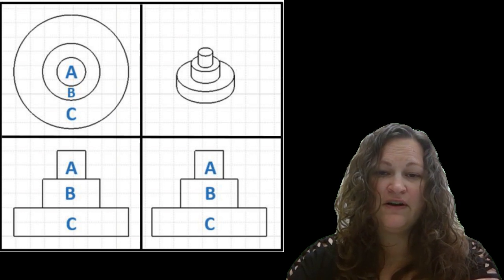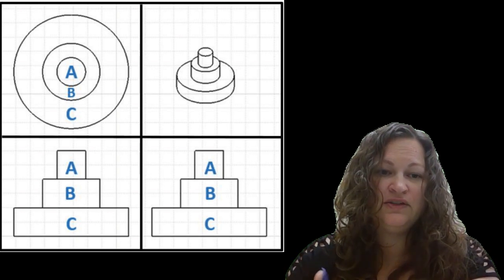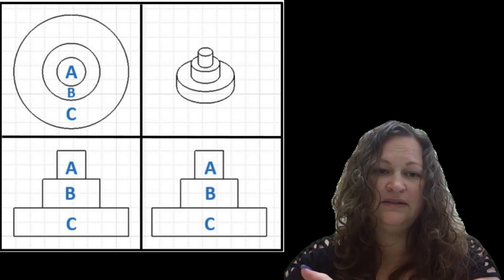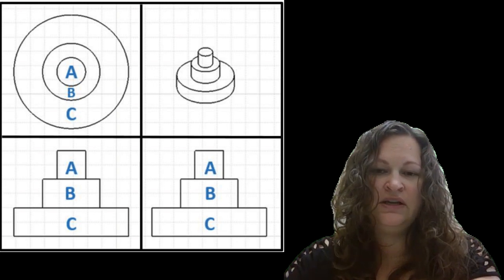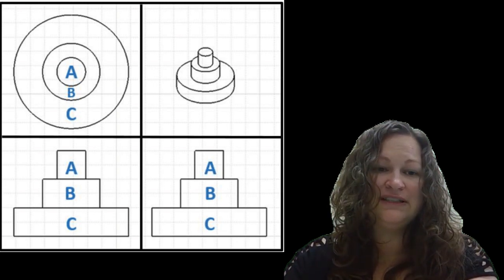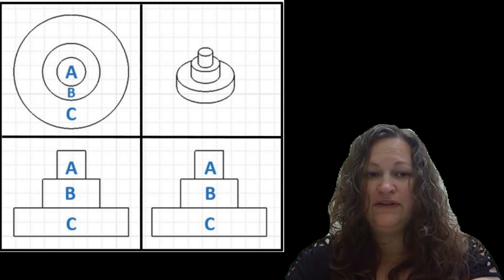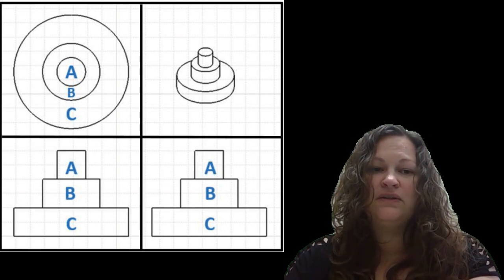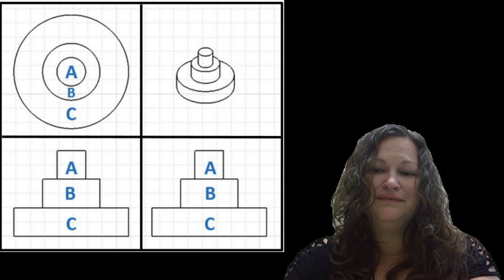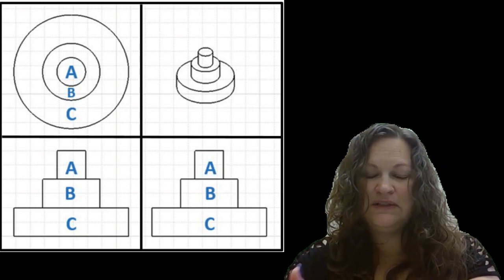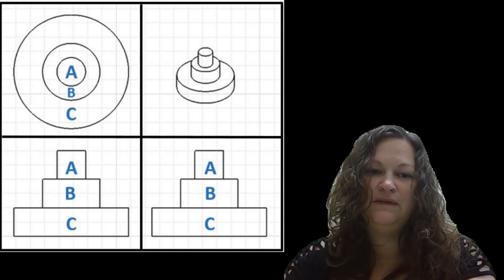Cylindrical surfaces are pretty common and illustrate that your object is being rotated around an axis and has symmetry in that rotational direction. So whenever you're interpreting a drawing, you're going to see cylindrical surfaces as a circle on one view and as a rectangle on the two adjacent views. So if you end up with two views that look identical, those are considered redundant views. So you don't necessarily have to include a redundant view in your drawing.